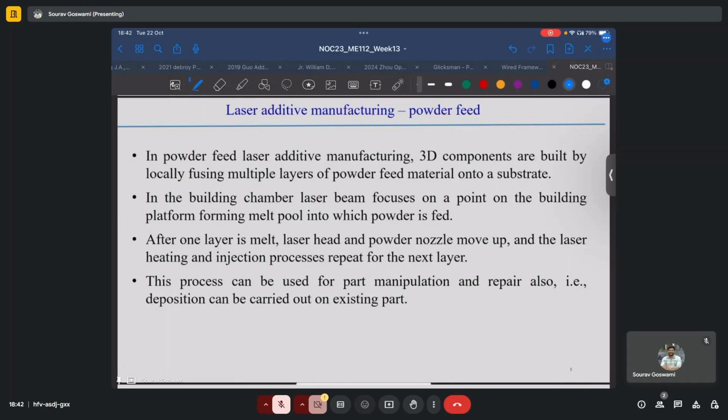In this case, the powder is directly deposited only in the regions where it is needed, in synchronous motion with the laser. The powder is delivered in the path of the laser via carrier gas, and it absorbs some energy from the laser beam, which may lead to a temperature rise or in certain cases even melting of the powder during its flight path. Then this fully or partially melted powder is deposited onto the bead and leads to the formation of the printed part.